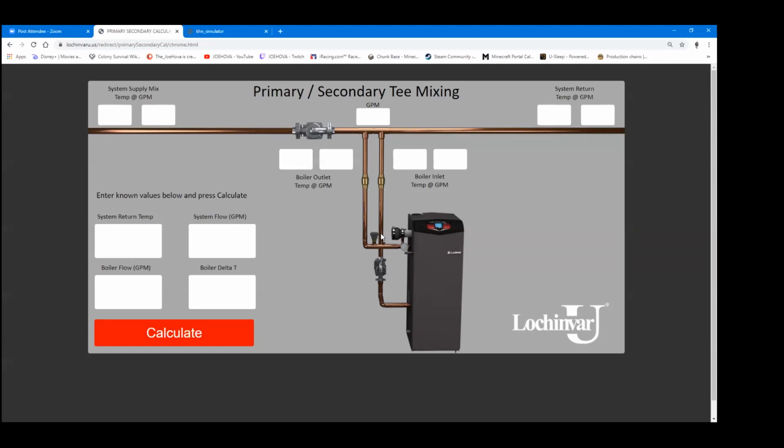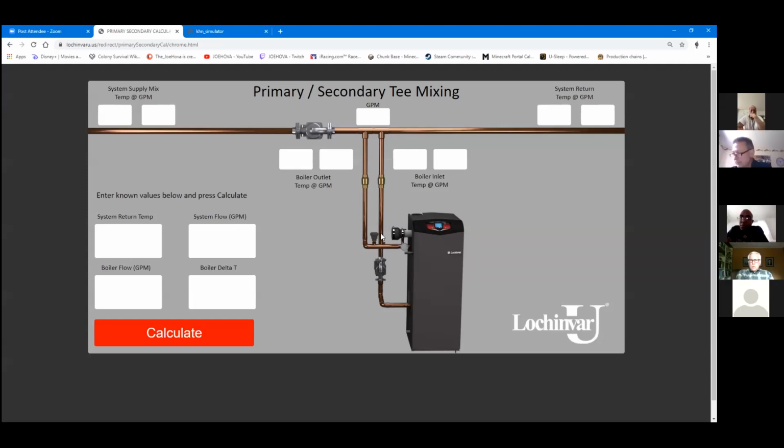We could do full flow systems on any boiler, water tube or fire tube. The reason we made the rule that you must do primary secondary on a water tube wasn't because it's impossible to do a full flow system, but it was just not practical. There were not enough controls in the system to actually maintain the proper delta T's. That led to flashing to steam and all kinds of bad stuff. Well, these units aren't going to flash. I mean, especially if it's a fire tube, because there's actually water capacity there. They're not going to flash. But what they will do is they'll modulate up and down in short cycle and create a mess. So we still want people to use primary secondary whenever possible.